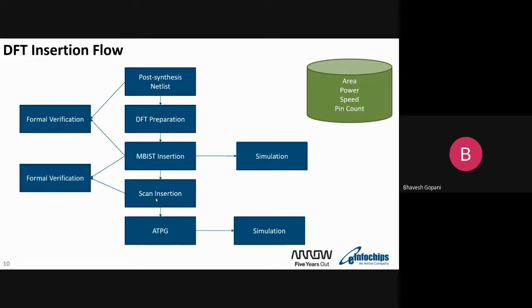Another thing is we can't do scan insertion on the memory, because if we insert the logic inside the memory, this is not a viable solution, and even on the output of the core logic as well. So once memory insertion is done, we can fix those timing constraints as well, or SDC, there are delay constraints. So timing related issues also we can avoid.